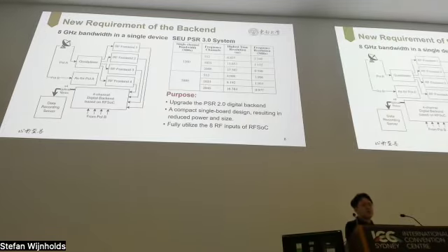So we decided to handle these 4 channels in a single RFSoC chip. The available modes are shown in this table, which has a maximum bandwidth of 2 gigahertz, the maximum frequency channels is 2048, and the highest time resolution is about 4 microseconds for the 512 frequency channels.